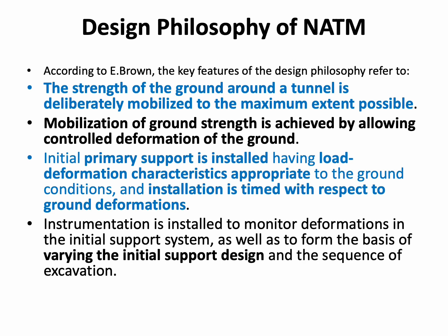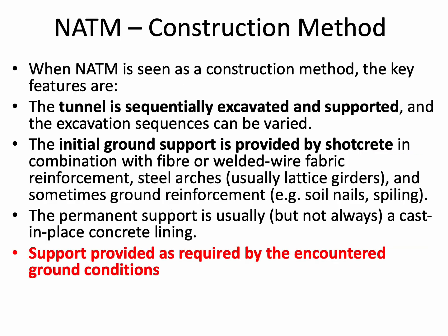Instrumentation is installed to monitor deformations in the initial support system as well as to form the basis of varying the initial support design and the sequence of excavation. NATM is more of a construction method.